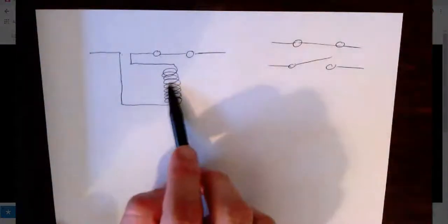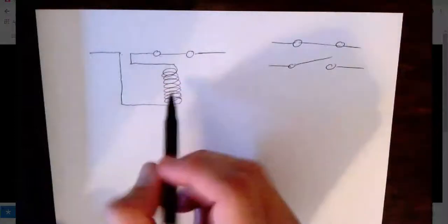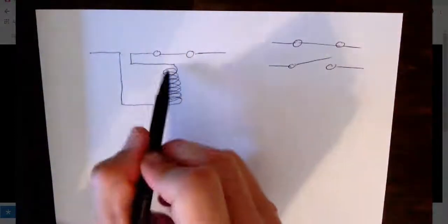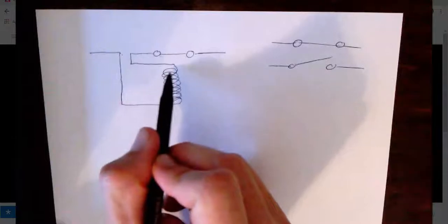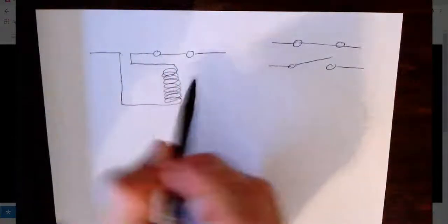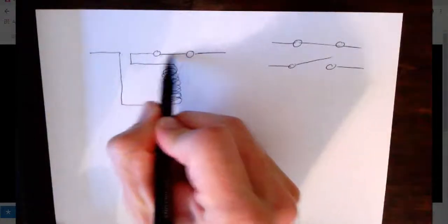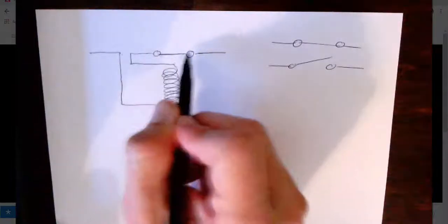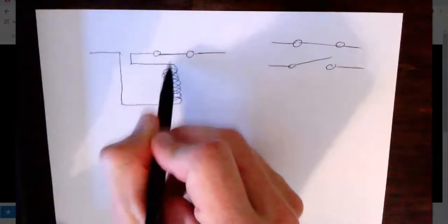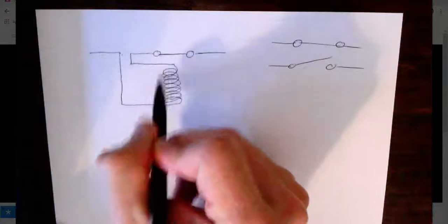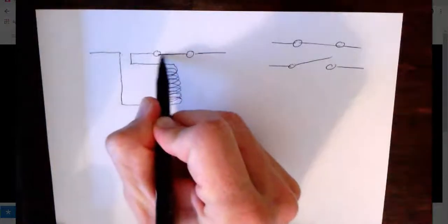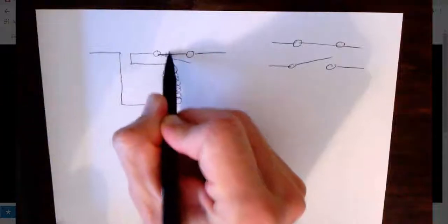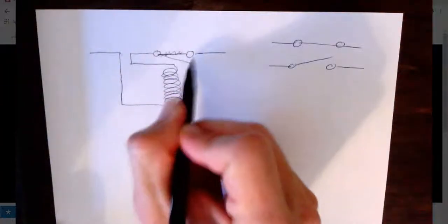But at some point, in its strongest magnetism, if the current in here is ever too high, this becomes a strong enough magnet. This thing here is made of iron, and even though it has some spring holding it, if this becomes a strong enough electromagnet, it can actually open that switch and pull this piece of iron downward, cutting off the circuit. The electricity can't get through.